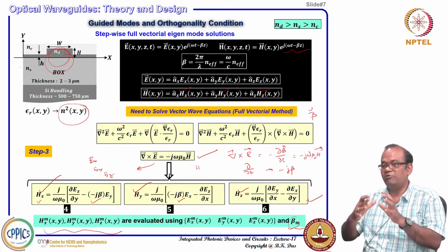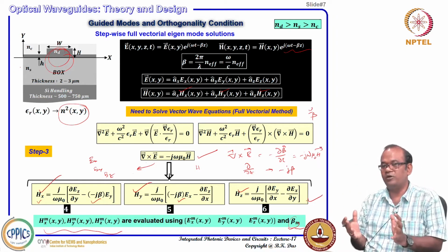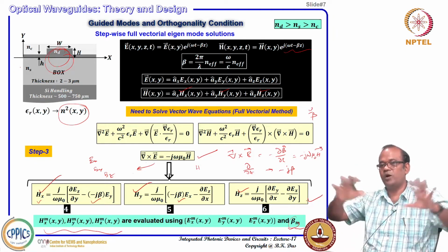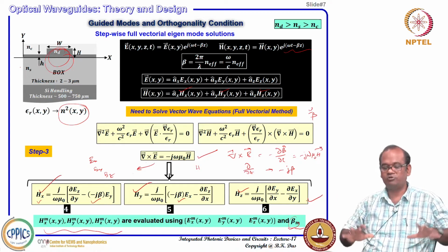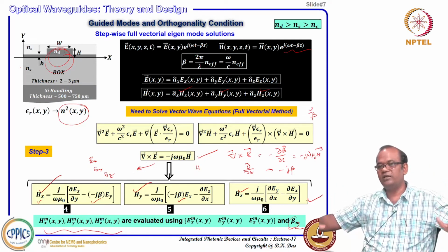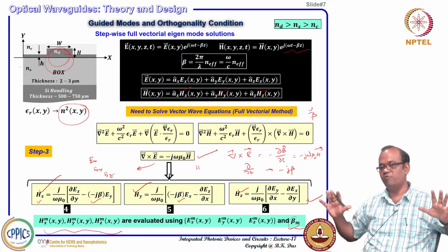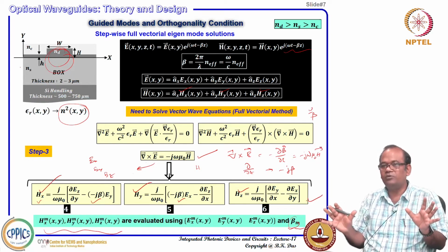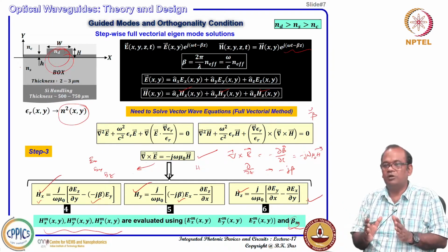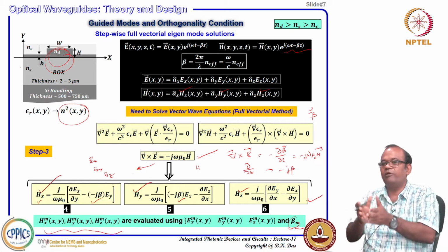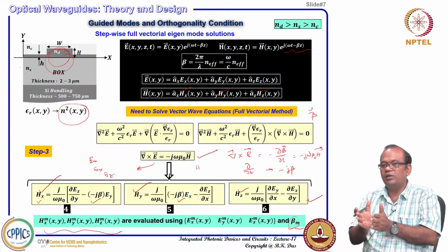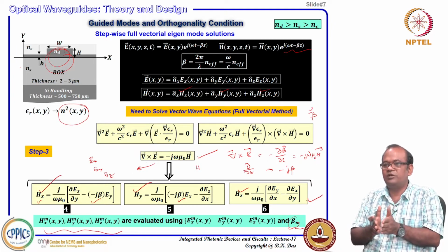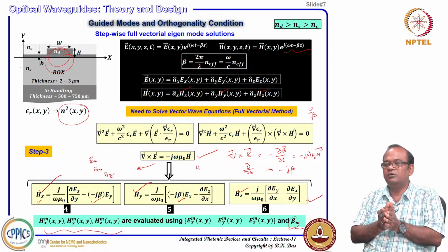If you see that you get a very well defined mode shape, and outside, at x y, the field is decaying slowly like an evanescent field, then that is a guided mode; otherwise they are leaky modes. That is the way we normally do it, because when you are using a certain technology and you have to rely on that technology, you want a structure which is comfortable to fabricate using a standard technique.